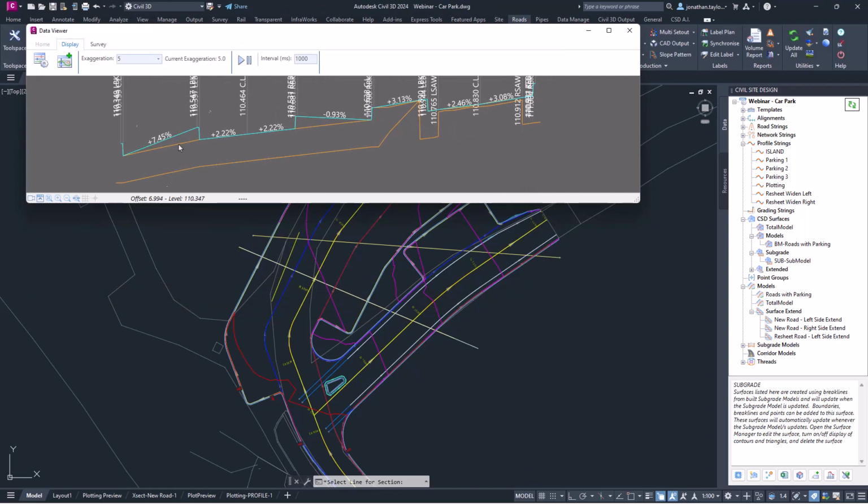So this is now showing me where my surface would be. This is my built model surface, which as you can see, because it's picking that original curve up from the road cross section, isn't quite right. But I expect this command will at some point improve. You can see the subgrade surface in here as well being applied. There's a surface resolve, as it's called, in the Subgrade Model Manager, followed by the remainder of the design. So take this with a pinch of salt.